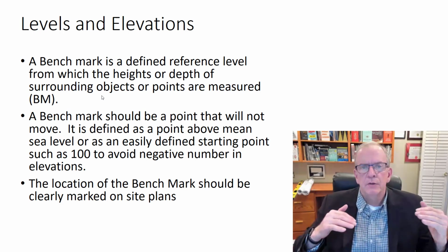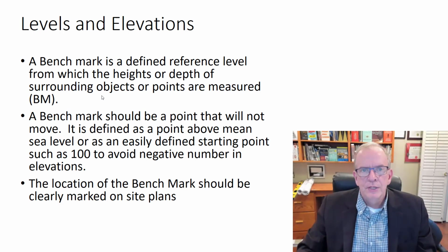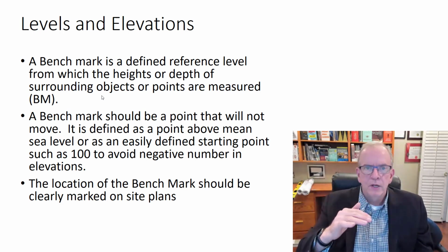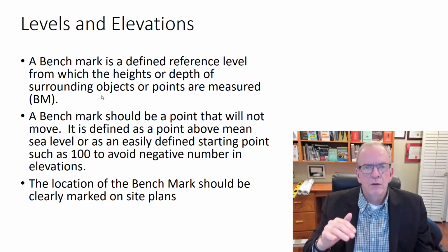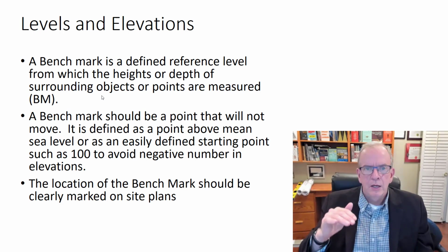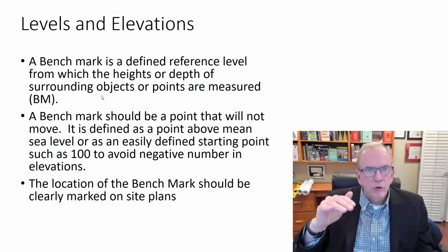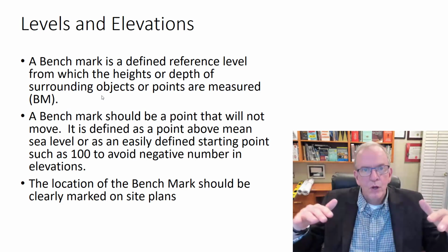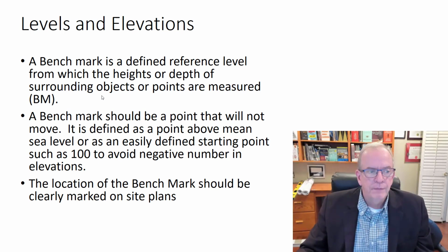And everything is sort of laid out and been measured, surveyed over the years and decades, and there's markings in every town and city at what the elevation points are, and they're reference points that whoever is laying out the building can reference from, so that the elevations will tell you how deep you can go, so that the footing will be at the right depth, so when you build the actual building, the first floor will be at the right amount above the finished grade. And the finished grade, what elevation do we want that? So everything is referenced from a benchmark, which is important from that perspective.